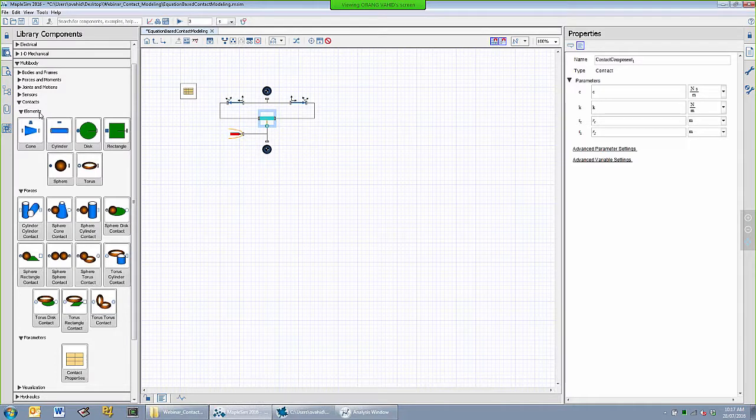You notice that in this custom component we had to explicitly define the geometry. What is a cylinder? It's a length and a radius, and orientation. What is a sphere? It's a point and a radius, no orientation. And so information such as that is required to be provided to the contact calculation.